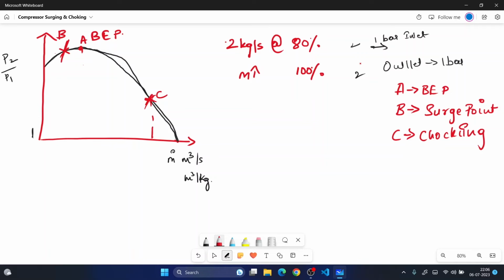So we all know from the equation of continuity, that is a discharge, we'll get the mass flow rate, say m dot, that is the mass flow rate equals velocity times area times rho. Since we are dealing with gas, rho comes into play.